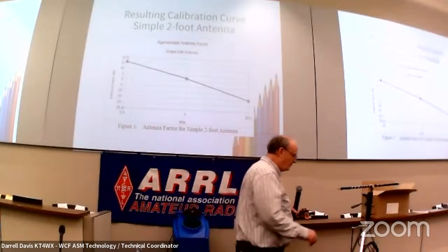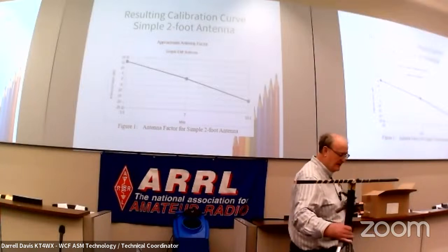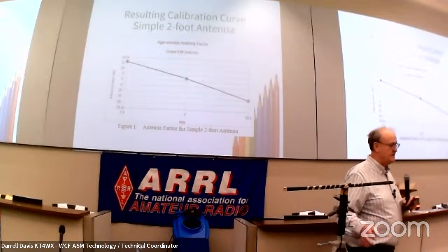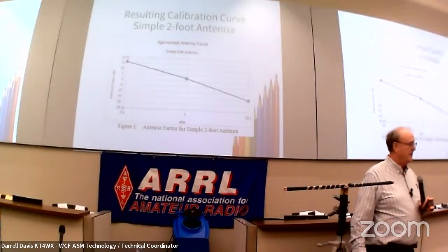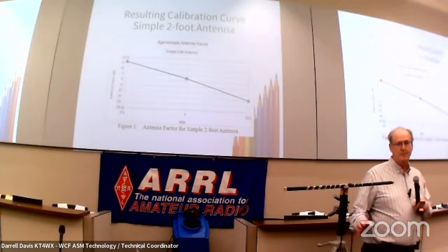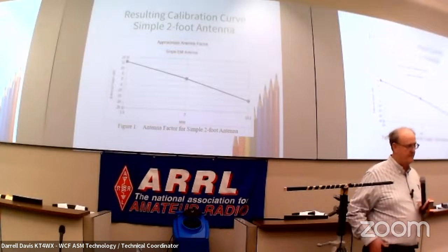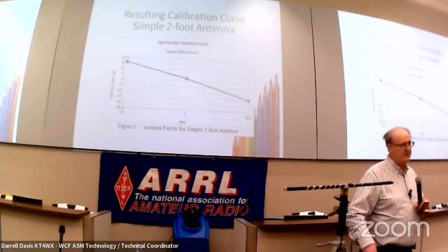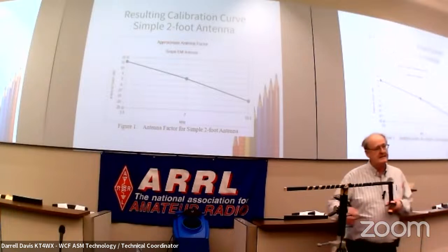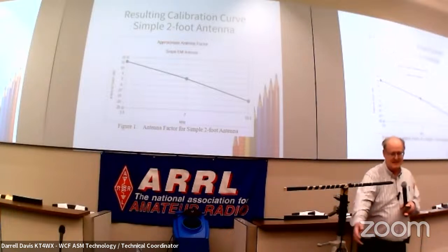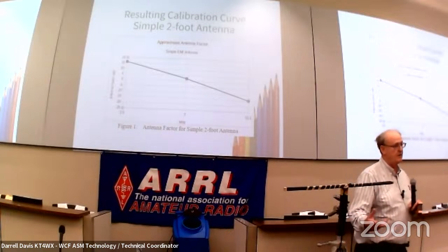And then this has a 10-foot RG8X cable, and that is part of the loss system because this is certainly not matched. It is not tuned. And so that introduces loss, but that gets built into the antenna factor for each band. And so it's inside the fudge factor. It goes into a 50 ohm spectrum analyzer, a Siglent in my case. But I can only get 10 feet away from the spectrum analyzer because that's all the length of this cable. And if I add more length to it, I'll change the measurement because the loss will get worse.